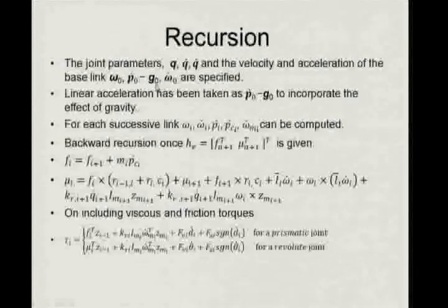So that plus there is another one also, right? F is equal to capital G into m1 m2 or small m capital M divided by r squared. So it's just one of the biggest coincidences of physics that these two masses turn out to be the same, right? So people are still trying to solve it as to why the two masses are the same, but luckily for us it's same. We'll take it and we'll accelerate the base of the robot instead of writing the g terms on each and every link.